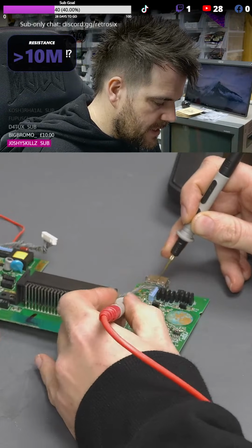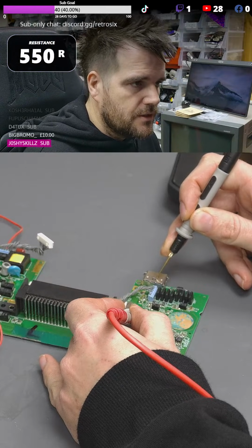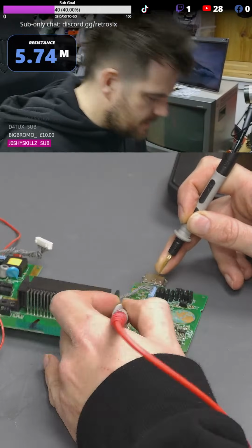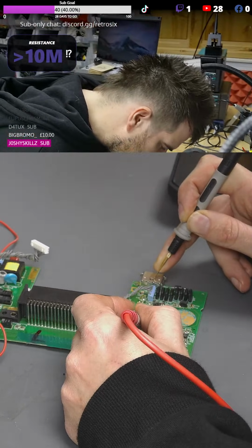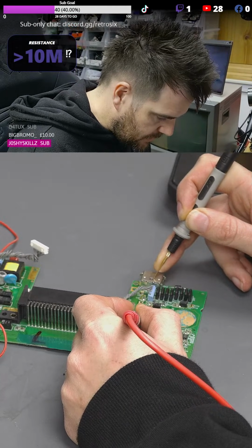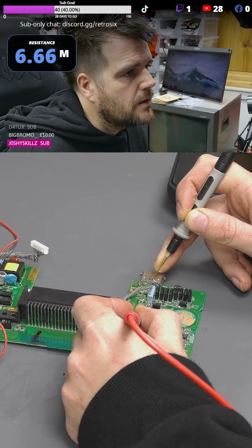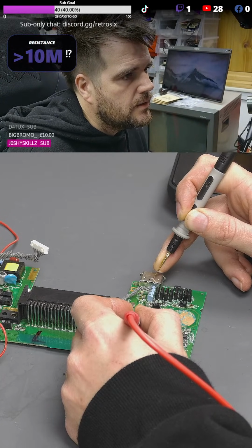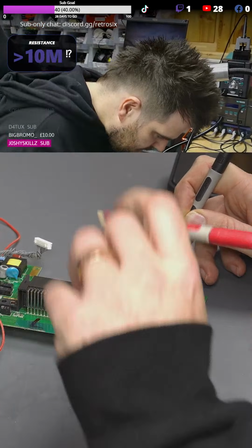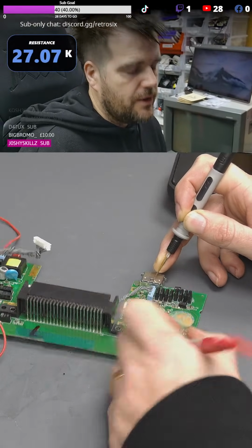We could go on the ASIC. One of these ASICs is actually ground and another one's 5 volts. So I think 5 volts is the bottom. Actually, no, I think 5 volts is about 6 pins down on here somewhere, typically. No, let's go on the cap. Probably easier to go on a capacitor over here, say. So this would be the 5 volt rail. Oh, I know why we're not getting it.